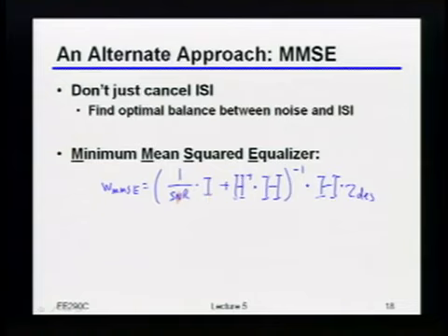The unit for SNR is in voltage, or voltage squared to be more precise. In other words, SNR is the sigma squared of the signal divided by the sigma squared of the noise. Remember, before we didn't have this term at all. It tells you that if your SNR is small, then forget about what the channel is. You're only going to set your gain based on just what the noise is.